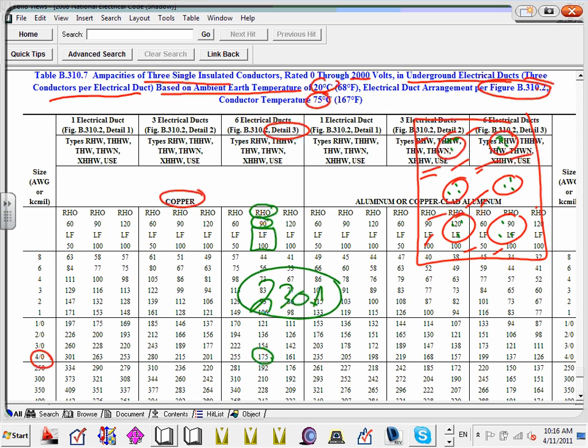If you put your conductors in underground ducts and encase them in concrete, a lot of people, guys, use 310.16. When you guys size the 4,000 amp switchgear for me, we shouldn't use, technically, 310.16. We should be using this table. Any questions, guys?